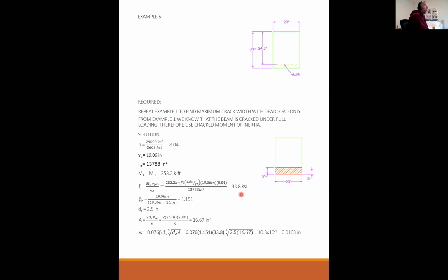So what do you do about this? Well, you can put more steel in there. More steel will lower this stress, or the moment of inertia also. So you could make the beam deeper, and that probably would be the most effective way to control this, is to make the beam a bit deeper and or add some more steel.